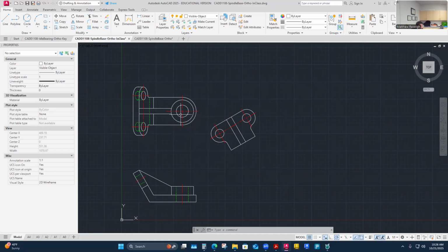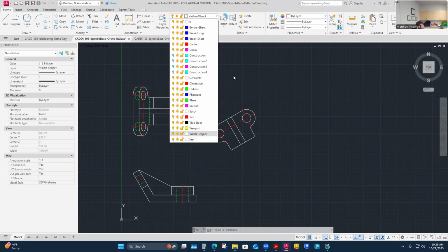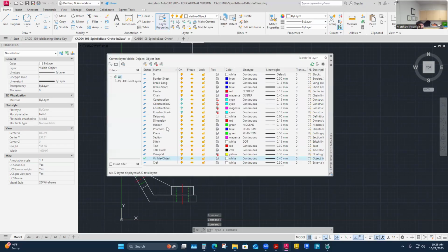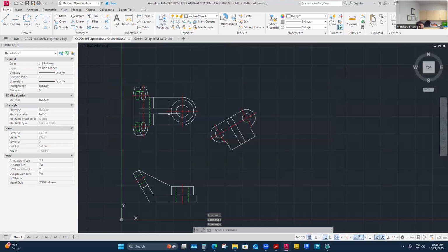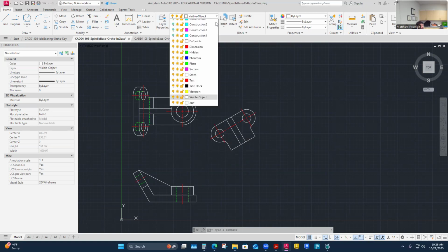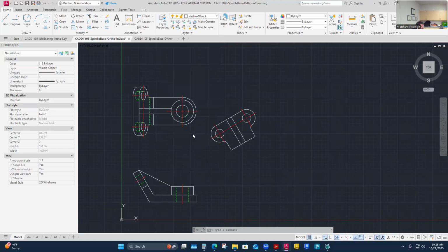And so sometimes I'll move these to some layer. Here's what I do. I mean, you can do this a lot of different ways. But if you have a part of your original orthographic projection that is showing up in a viewport that's annoying you and you can't quite get it to cut out, I just end up moving those to a layer that's turned off. And when I move those to a layer, I generally make another visible object layer.